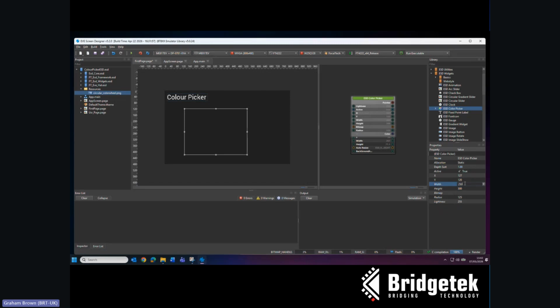We can use the properties window to set this to the size of our input image, so 250 by 250, and then we can use this bitmap drop-down to select the image we want to use. As you can see, it's emulated on the screen here on the left-hand side.